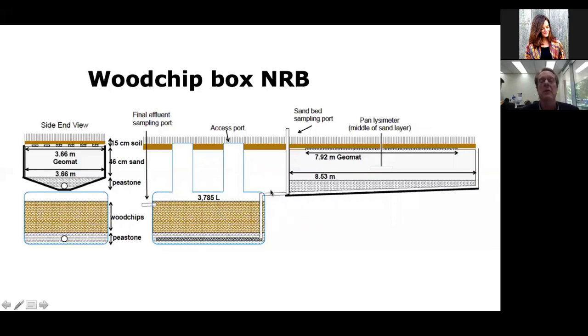It goes from the sand layer here, down into deposition here, and then into the wood chip box, which is in here. Turns out it denitrifies very, very well, even though it's a very small volume compared to the layer cakes. And I'll talk about that research that we're doing into using those with IA systems in just a moment.